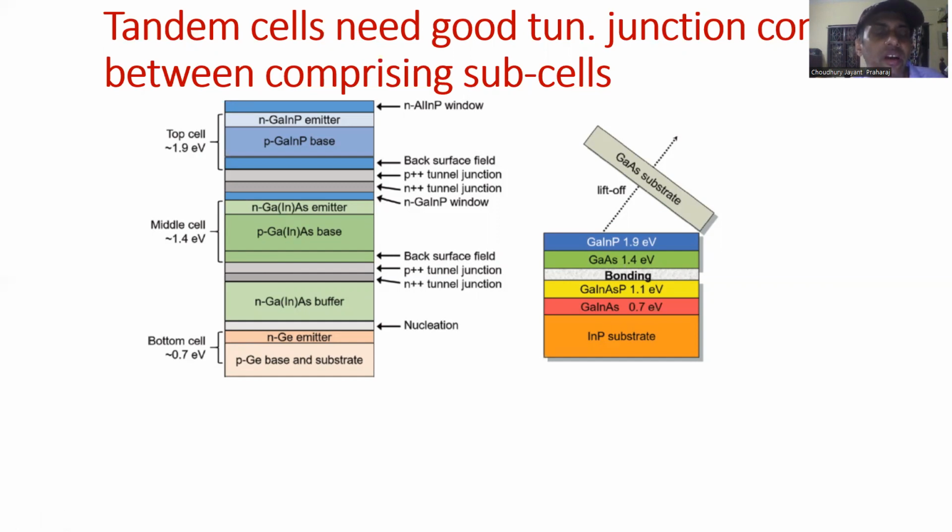And as we mentioned, because the P layer is difficult to get more P concentration out of due to deep acceptors in these material systems, we need to specifically tailor the band profiles in these tunnel junctions to get good tunnel junction contact resistances, etc. And so this is a major design consideration, especially in this material system while designing tandem cells.